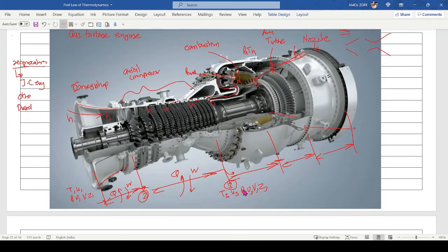If the fluid is compressible, its density would change depending upon the shape. Look at this, this is a reducing cross section, so this entire shape will act like a nozzle, so velocity would change. The potential energy, in most cases we can neglect it, because our engines will be horizontal. Even if it is vertical, or even if there is a difference according to your application, you can consider those parameters. Okay, so likewise, this is a fourth stage. This is the fourth cross-sectional location.